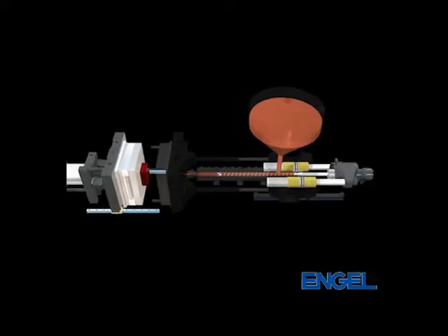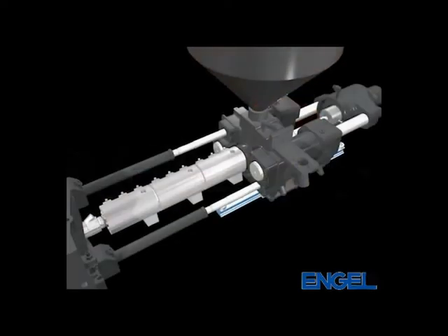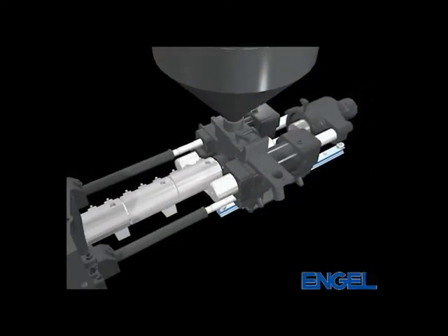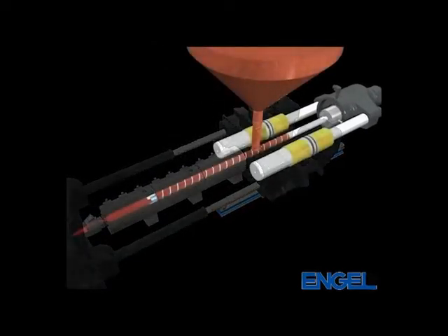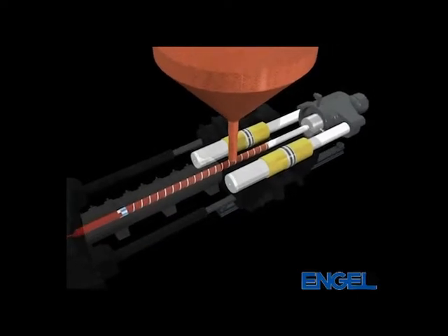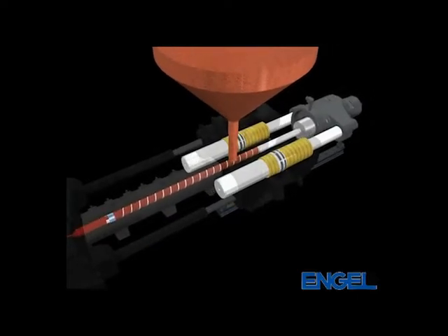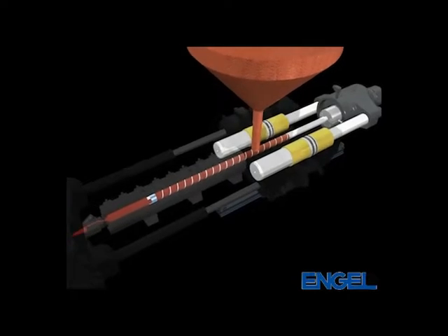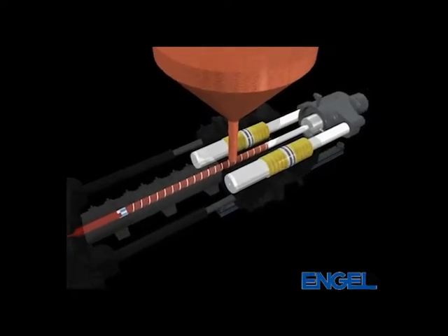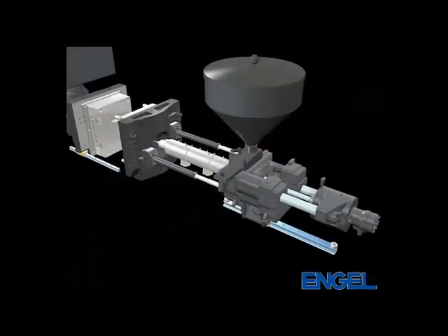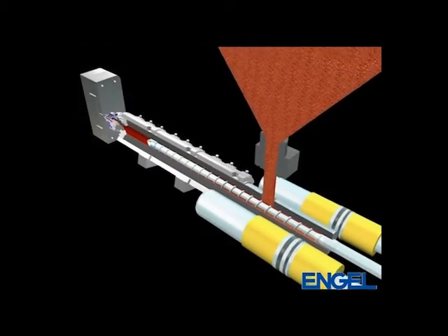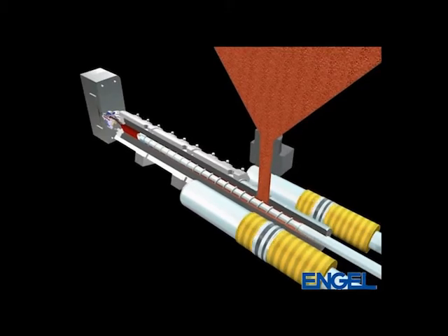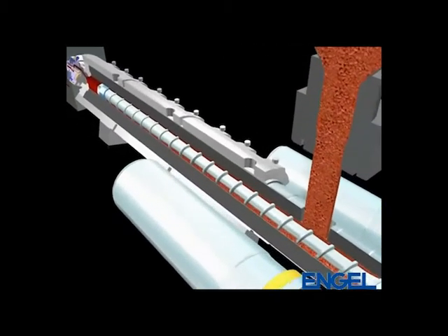The main difference is, at the end of this screw, we have a small valve. We basically have a check ring, because the screw is now no longer fixed. The screw actually moves backwards and forwards, which gives us our injection stroke to force material into the cavity. So the screw only turns as it moves backwards in order to convey material through into this melt reservoir here. Then the screw moves forward and this valve closes, and that's able to force the material into the cavity. So it's a little bit more complex than the standard extrusion process alone. But it's this injection action, this forcing forward as a ram of the screw, that actually forces the material through our nozzle and into our cavity, which makes the shape of our component.